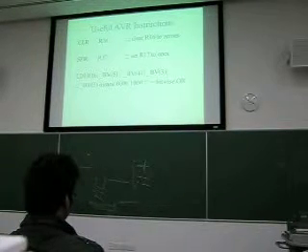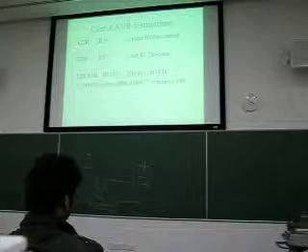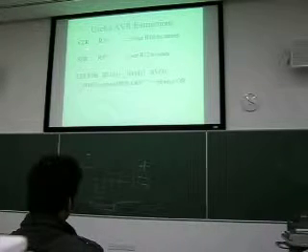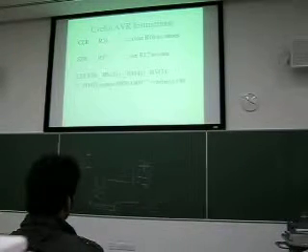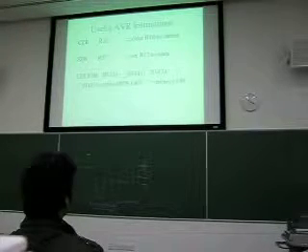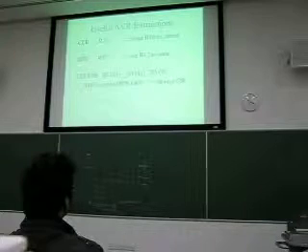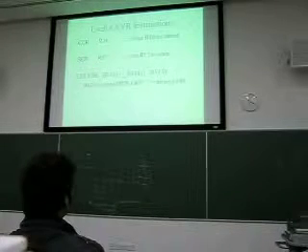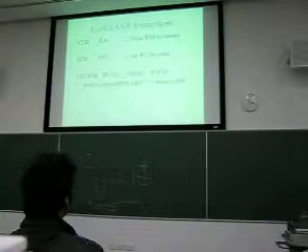Okay, some useful AVR instructions. So I suppose by now you should know that this is clear. All the values in R16 become 8 zeros. Whereas this one is the opposite. You set all the bits of your register to 1.